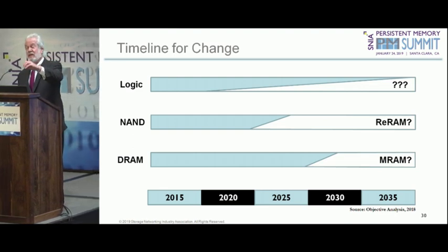These are the memories that go inside logic chips that are built typically in foundries, over a wide range of process geometries, from 350 nanometers all the way down to 22 nanometers. At the 28 and 22 nanometer nodes, it looks like most people are going to be using something other than NOR flash for their embedded memory.